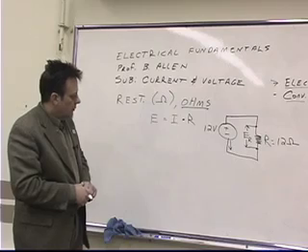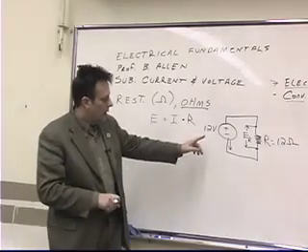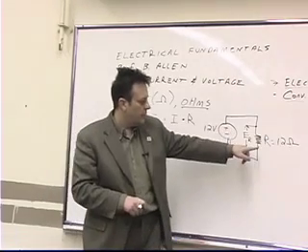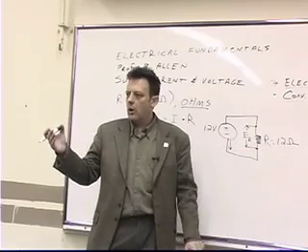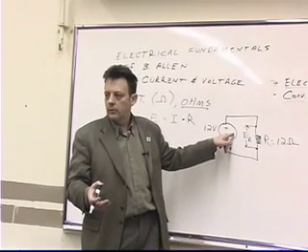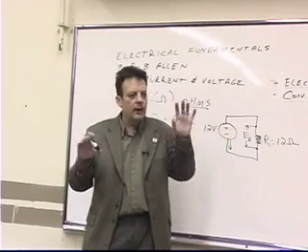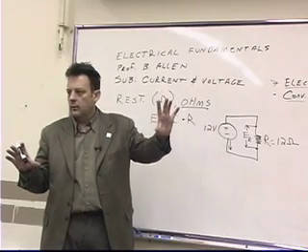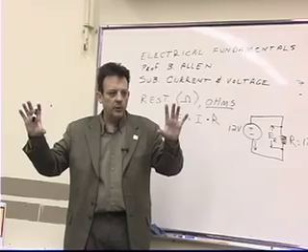Well, right now, what is it that we know? We know the voltage across the source, and because there's only one other thing in the circuit, later on we'll learn a law called Kirchhoff's voltage law, and that'll tell us that the voltage has to be the same here as here. But for most people it's kind of common sense that if you only have two things in a circuit, an active source, like a lead acid battery, and a hairdryer or a resistor of some kind, they're both going to have the same voltage on them.